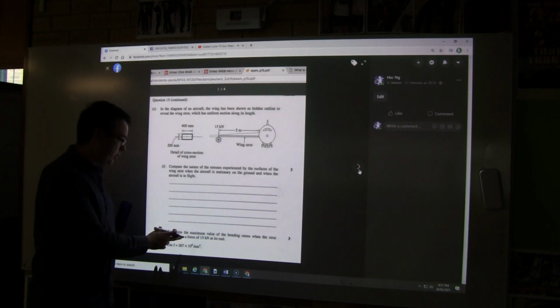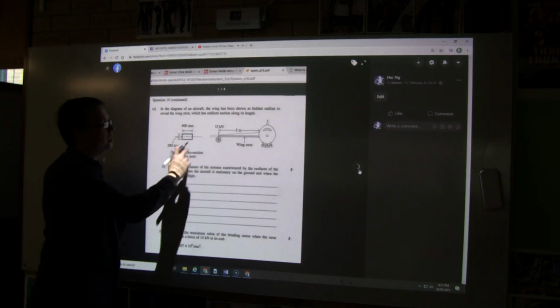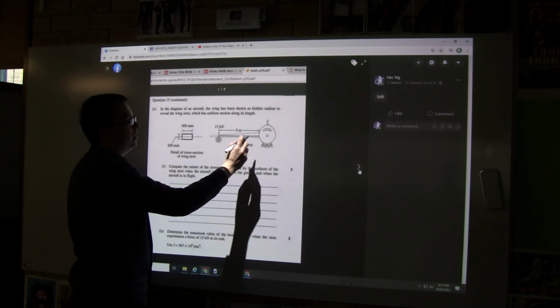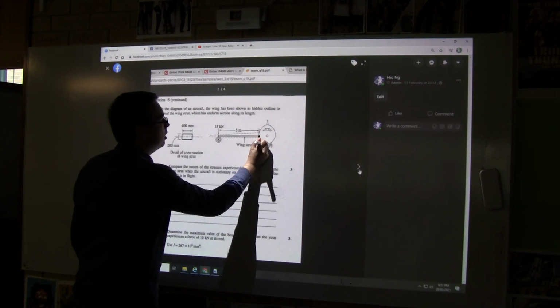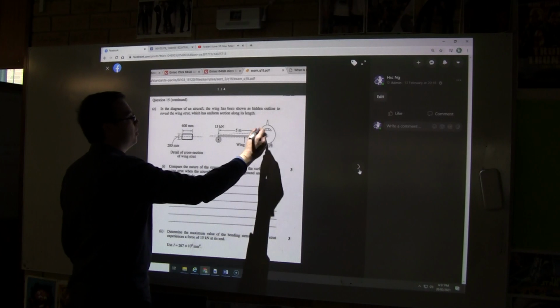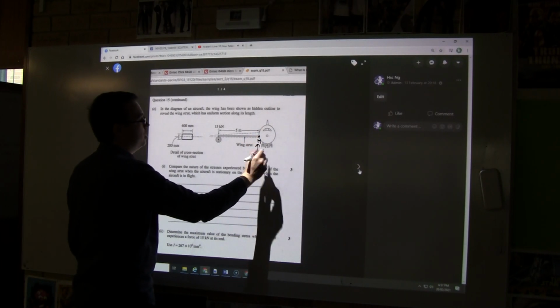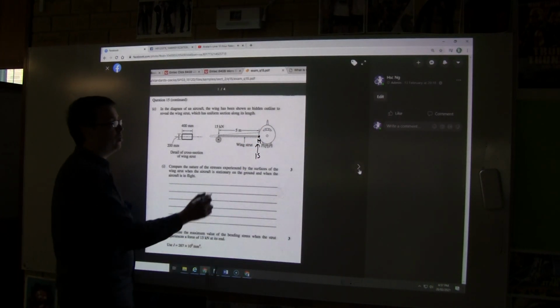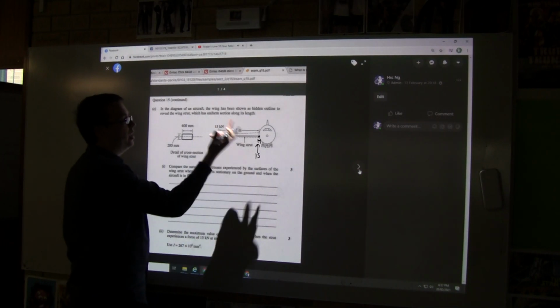They've told us that there's a 15 kilonewton force and 5 meters. So that means at point H, what have we got here? We're going to have 15 going up just to balance that equation. Sum of the forces vertically, 15 down, we need to have 15 up.